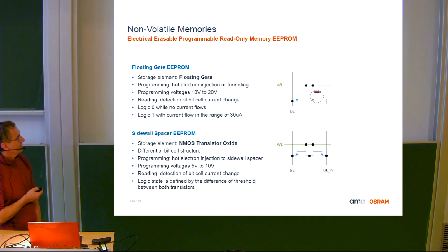And another technique like this, so this is a disadvantage, you need to introduce some additional poly. So this means additional process steps. This is something the fab doesn't like. So it needs a requalification, needs to change thermal budgets, all other transistors will be influenced, so they have to tweak around to get back to the standard flow. So you always introduce problems with that.